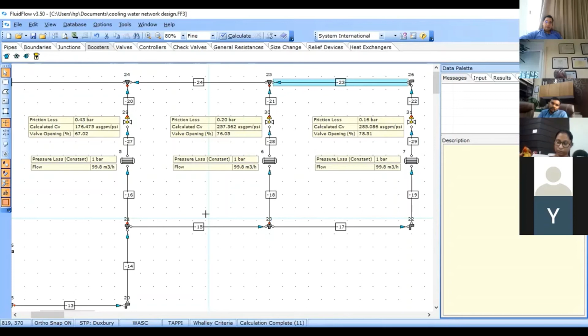So at that time, what will happen if I have the restriction orifice? Do you think the flow rate will reduce to 50? No, it won't, right? So at that time we'll end up providing more water. So on the process side, the temperature will be on the lower side, which may not be acceptable, right? So for that, if you have the flow control valve, then it will work fine. But yes, it is expensive. That we cannot avoid, right? So we need to actually check.